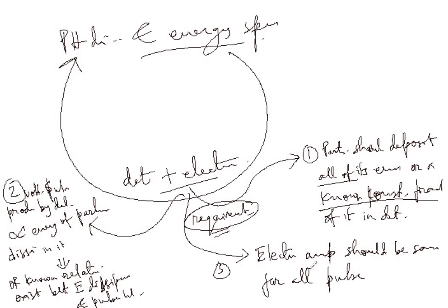What we want is amplification to be the same for all pulses. Linearity in response will be there. Okay. So you see, since the relationship between the pulse height distribution and energy spectrum depends on these requirements, it is very important to remember them.